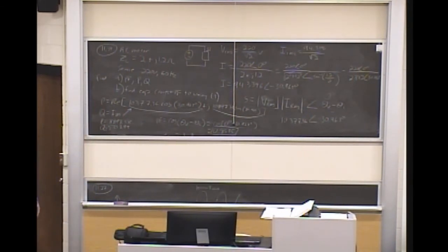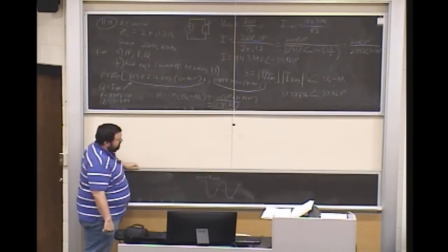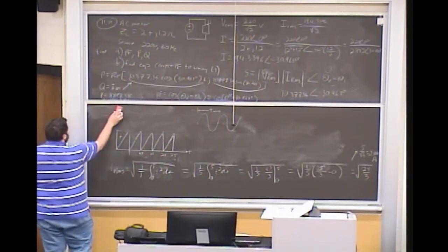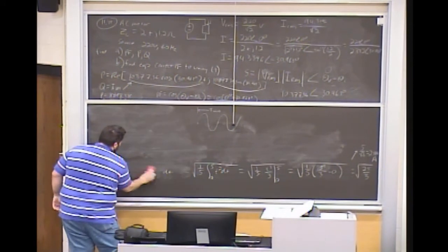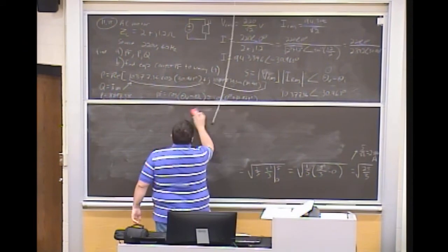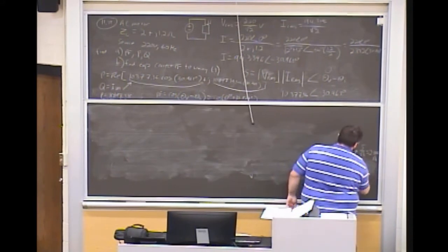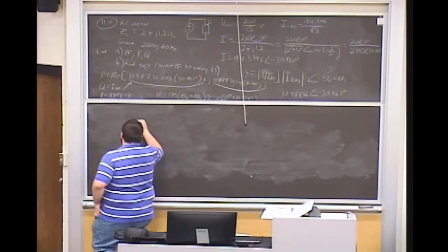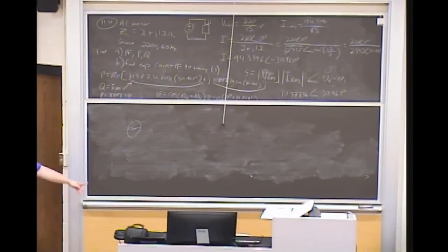So what can we do? Well, we can add a capacitor in parallel to this load. So effectively what happens is you've got an impedance right now as your load, which is modeled as effectively an inductance and a resistance in series. This is basically what you have. You have some sinusoid. So sometimes voltage sources are drawn like that. A lot of times if it's AC, we draw it like that.